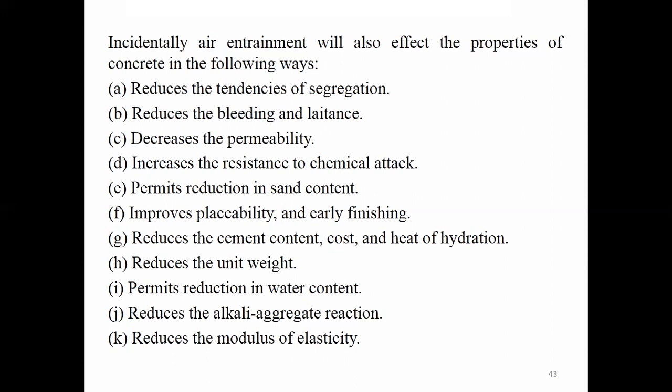To withstand that, the abrasion should be resisted. There is some criteria. One is the amount of air entrained. The amount of air entrainment should be less than 6%, then only the abrasion will be lesser. Lesser means the concrete surface will be capable of resisting the abrasion when the amount of air entrainment is less than 6%. In pavements and all, they will be adopting only up to 6 to 10 percent in range. So it will be a satisfactory condition when you are going for the pavement. That is what they are discussing.